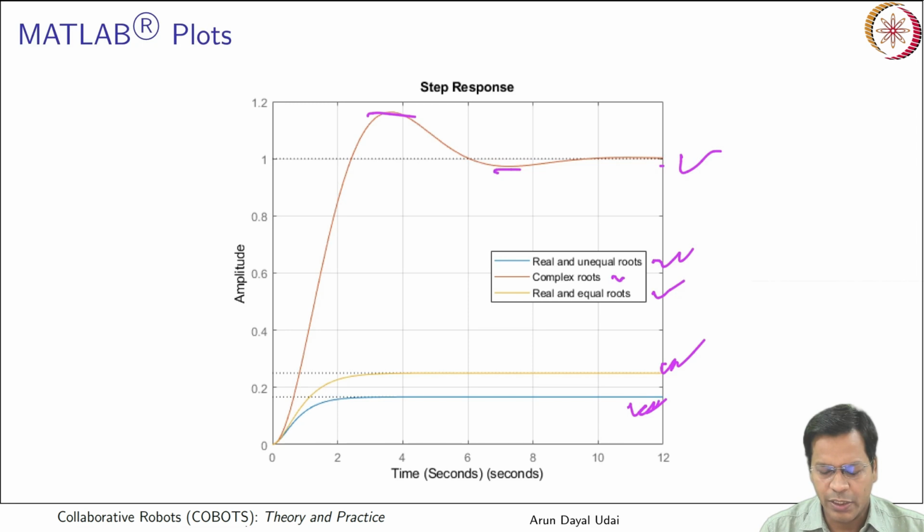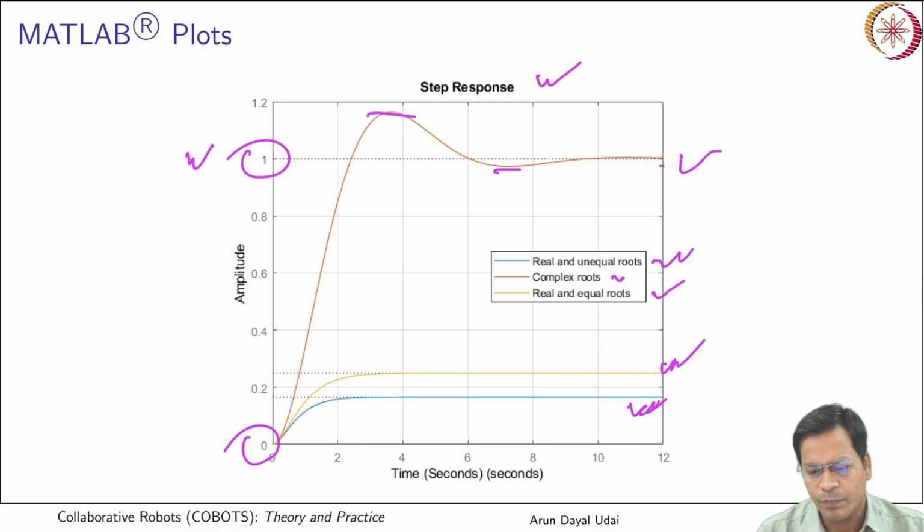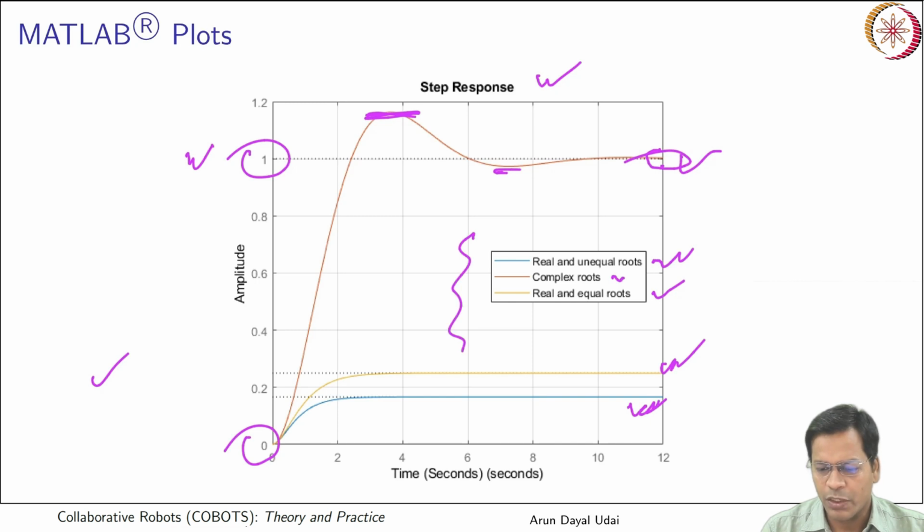This time it gradually, you were at rest, that is here. This is the step input response. So step was just 1 unit. So you quickly reach the 1 which is here, and you just overshoot it, came back, ultimately you settle somewhere over 1. For different roots, this is the thing which will basically define your system, and this is the behavior of your system. So these are the MATLAB plots.